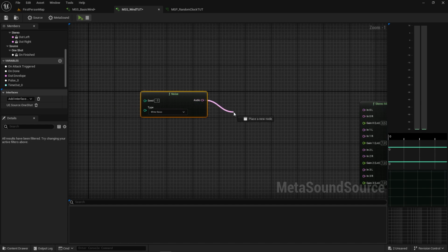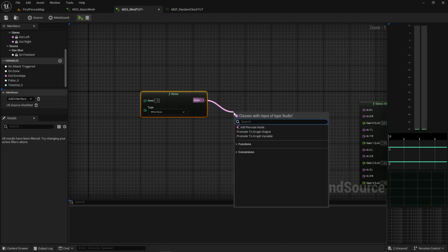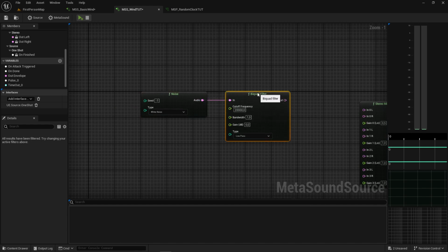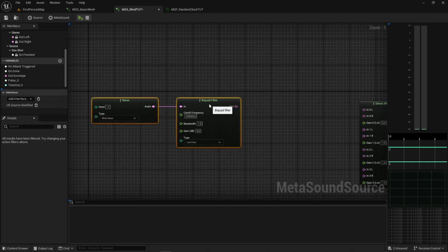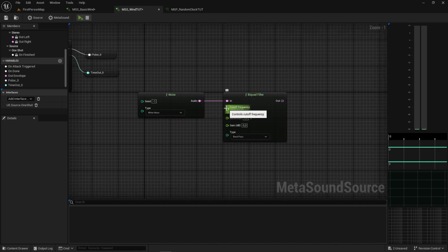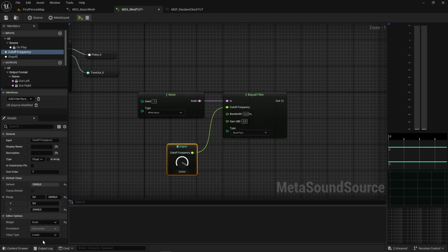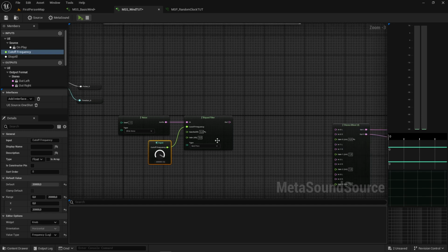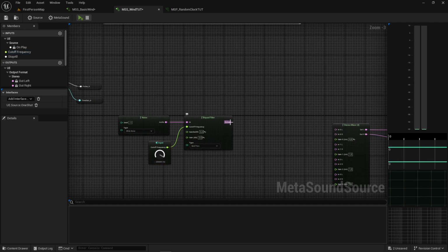do something they used to do in the old days. Hello, biquad. Biquad filter. If you don't know what a biquad filter is, it's a 2-pole filter. Then we need band pass. Bandwidth pretty narrow, just for the moment. I'm going fast, so I try to make it short. Let's give it a 3 dB, yeah, with a bit more energy.